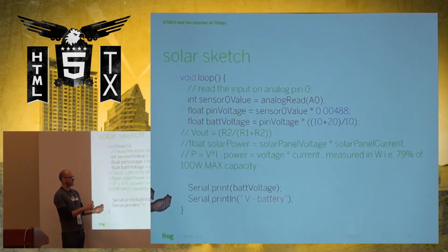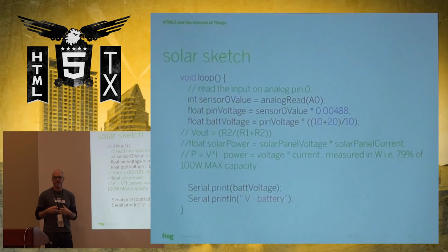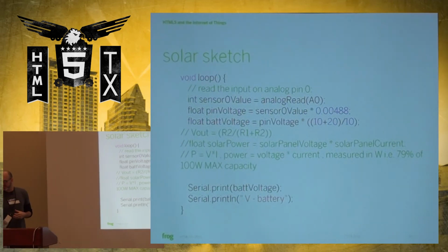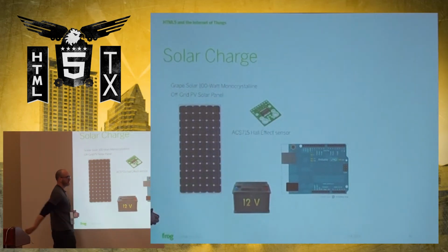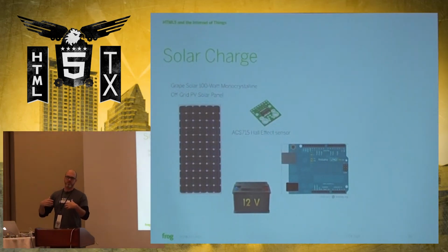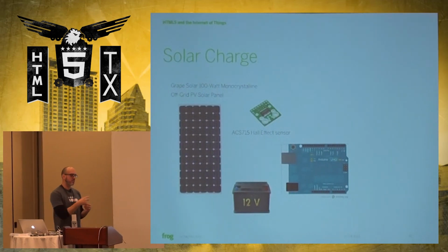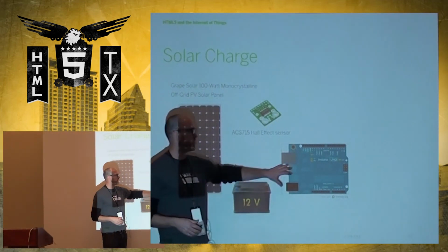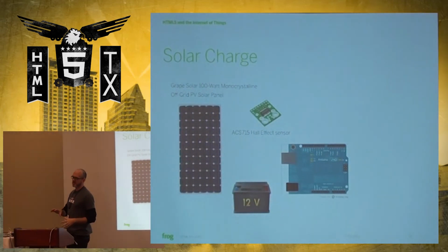So getting the current charge of the battery is just one thing. I also want to know what the pull is off the RV on the battery, right? So I've got that Hall effect sensor right here, which allows me to get a read on the current being pulled by the refrigerator, by the radio, by the lights. And then I can pump that over to a different pin on the Arduino and send it over to the web app. And then I can get a visual of that.